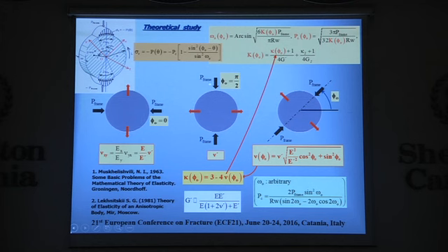Whereas in the other limiting case, when the external applied load is normal to the planes of elastic symmetry, then straightforward from the data we have this Poisson ratio equal to mu prime. And reasonably, I think we have simply assumed that in the case when the external applied load forms an arbitrary angle phi0 with the planes of isotropy, then the dilatation along this direction will be described by the aid of this Poisson ratio.